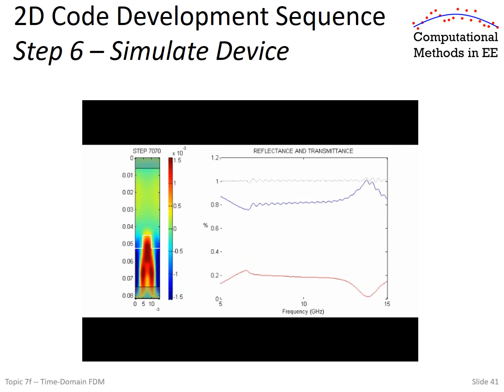So we can conclude, okay, we now have a working two-dimensional finite difference time domain. Notice we took it through a very similar set of incremental steps like we did for the one-dimensional finite difference time domain. This is very representative of how I write my own codes. The more steps I can add, the better. I never ever just jump into the big, bad, ugly thing that I have in mind. I build it in steps of increasing complexity. That's a very, very big deal and great advice to you writing your own codes.